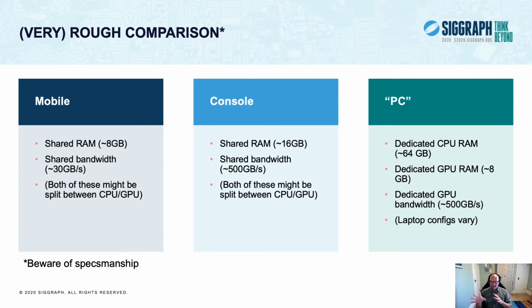So at this high end of things, discrete GPUs targeted at tethered systems have lots of local or dedicated memory. They'll have, literally on the graphics card, graphics RAM that is there just for the GPU, and traffic doesn't have to go across the system bus for that. It just has a very high performance local bus that provides the GPU with all its bandwidth.